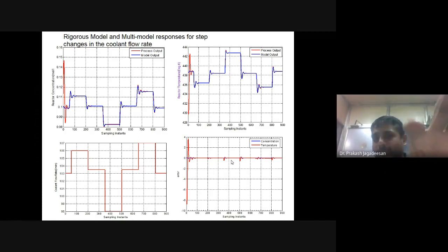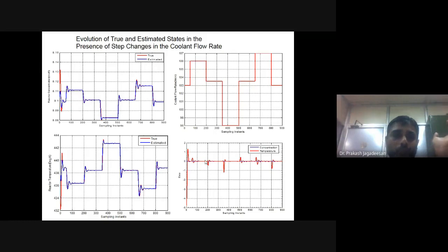So with the help of the reactor temperature and the mathematical model, we developed a soft sensor. What is available to us is basically the temperature, the input, and the mathematical model which we have developed. So using this, we estimated how concentration is changing with respect to time.